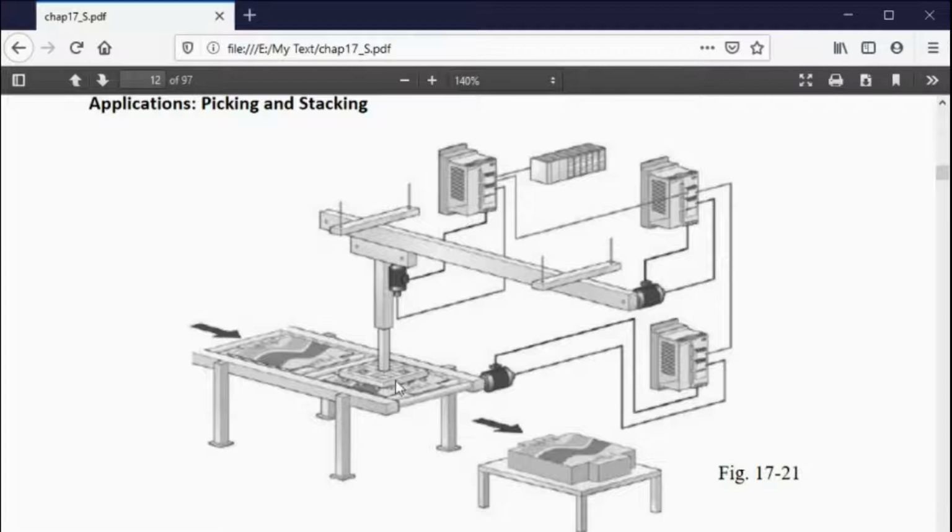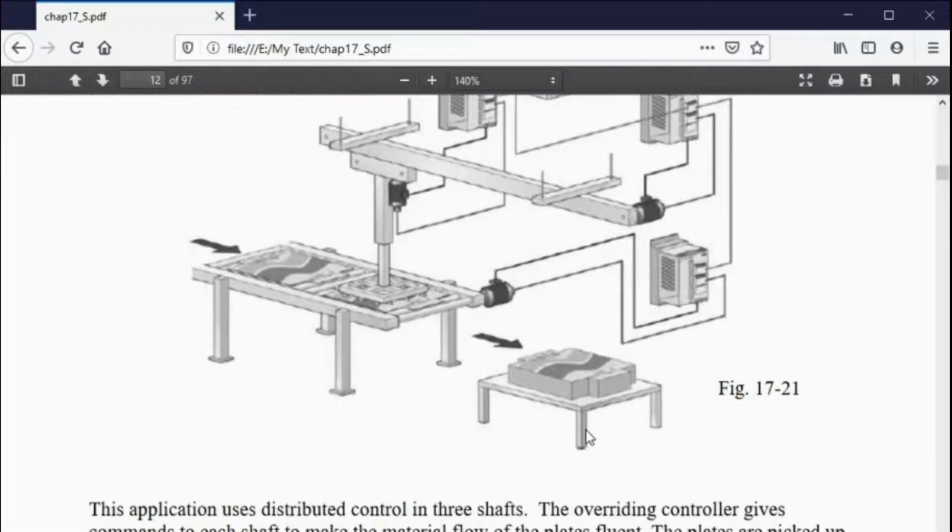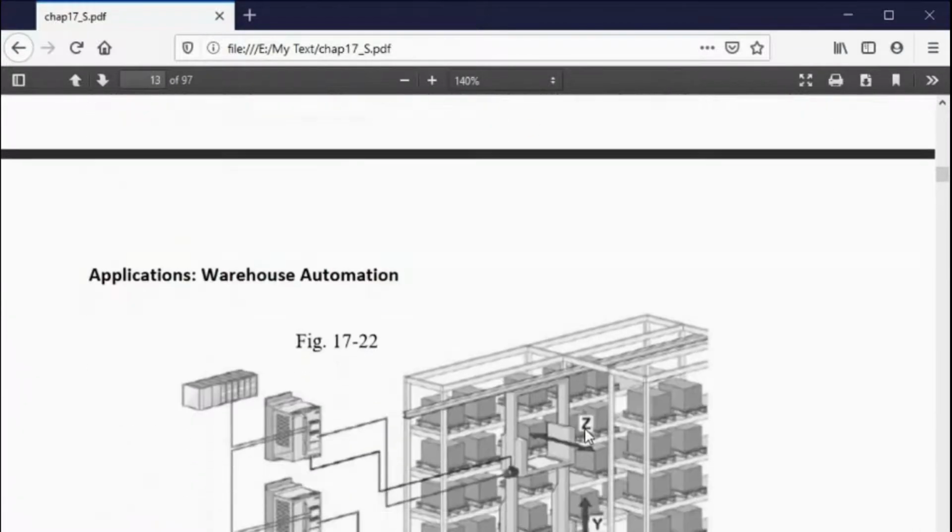So we move the part in. That's this motor right here. We stop it, then we pick it up. We bring it up to a certain height, move it over. That's another motion, and we place it back down. Those are all single axis applications, and it is not critical that the 2 axes talk to each other in a sub 1 millisecond time frame. So those are not coordinated.